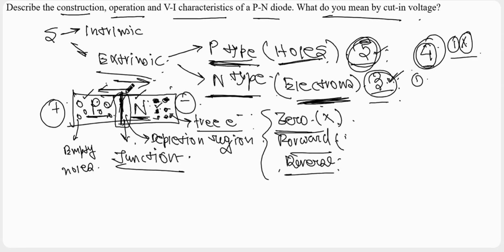So this depletion region, suppose this region is like this. So the box now will become small like this. So the depletion region will decrease. Okay. And the depletion region resistance becomes negligible when the applied voltage is large. In silicon, at a voltage of 0.6 volt, the resistance of the depletion region becomes negligible. So if we apply a 0.6 volt bias externally, the resistance becomes negligible.